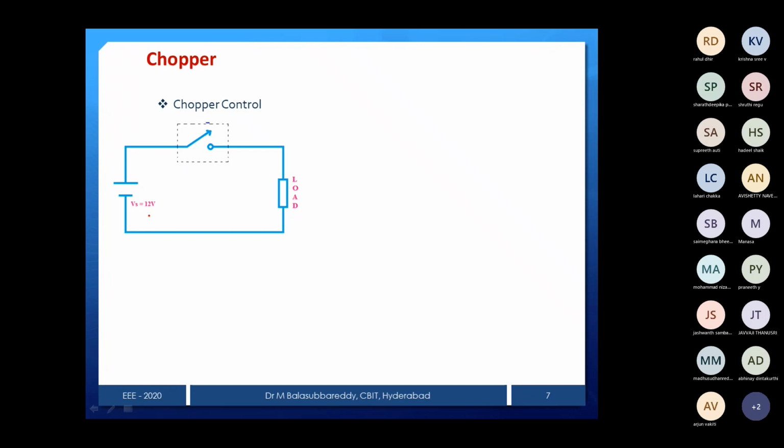and the switch is going to be turned off. So now we'll see that there is a 12 volts input we are giving. Then what is the output voltage waveform if we are able to fire the device? Let it be that for some duration I turn on the device and for some duration off, again on and off. This is your firing pulses, IG.